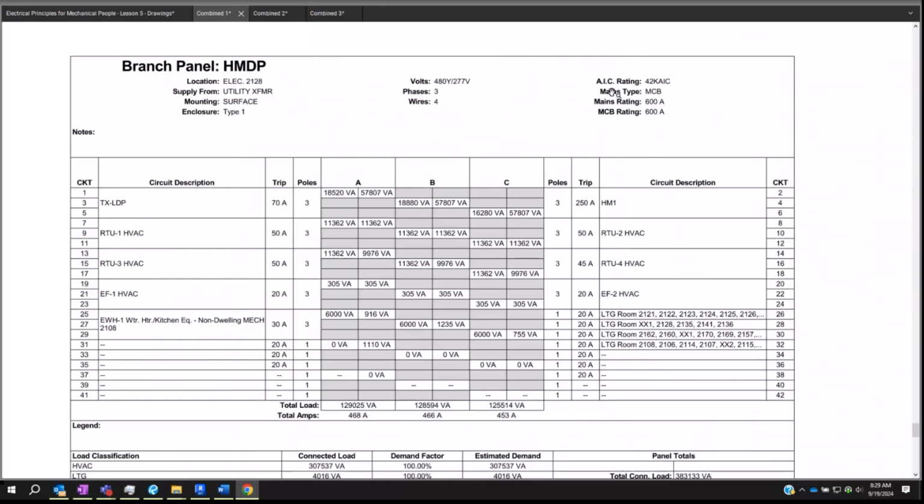All right, let's say I've got a very large switchboard open because it's easier. And I've got a very large wrench in there because I'm trying to tighten a nut. And I drop this wrench and it lands on all three bus bars, and there's a massive amount of current flowing because it's a very large wrench. This is the most amount of current I can pull out of this system. I've still got to be able to open the breaker. I've still got to break the circuit depending on how much current can flow in that scenario. It's called a bolted fault.